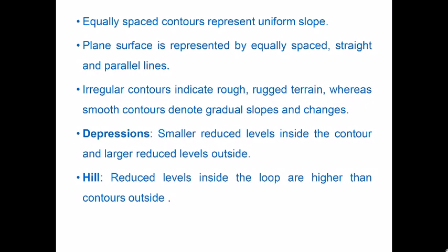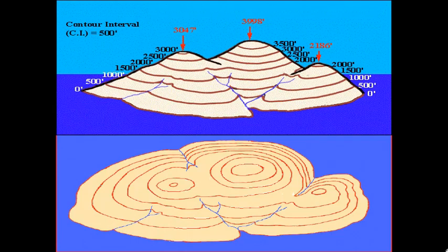So this is everything that we have discussed up till now. So let's see this figure. We have this sort of topography where we have three peaks in this mountain region. And when you draw the contours, we have this peak which is the highest, and we have this one and this one. And when you draw the contours, you'll have three sets of concentric irregular circles. And if you go beyond them, you'll have these bigger circles which join all three hills, the base.